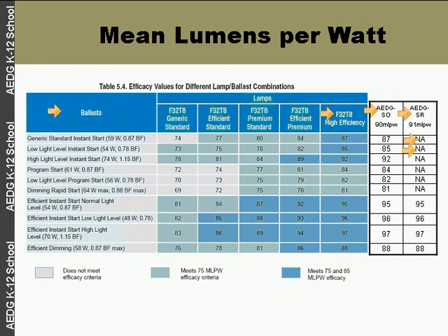This was a guide, again, that I was involved in. And this was also a guide that we did need the savings from daylighting in the warehouse spaces to meet the 30% goal. In the 99 standard, again, the base was 1.2 watts per square foot. In the 2004 standard, it drops to 0.8 watts per square foot.